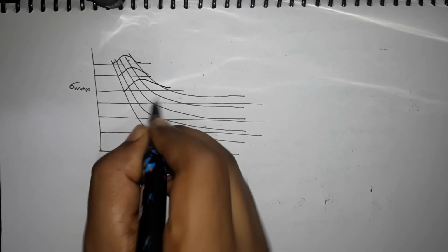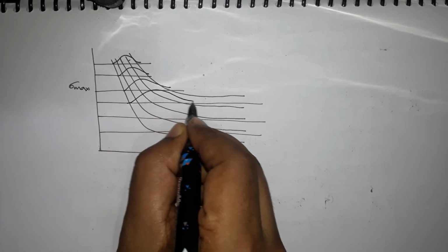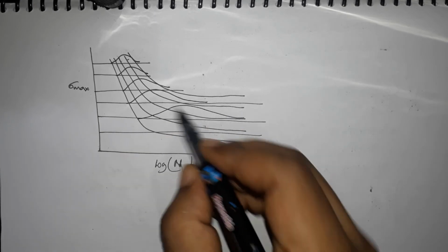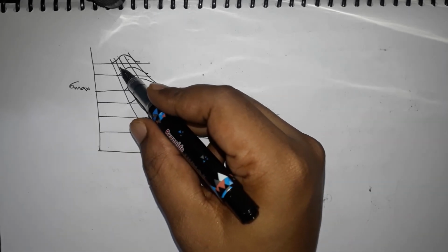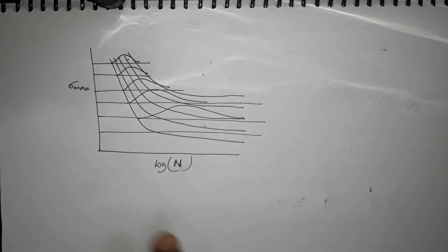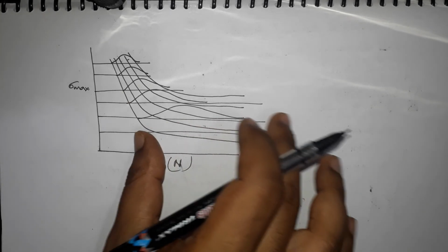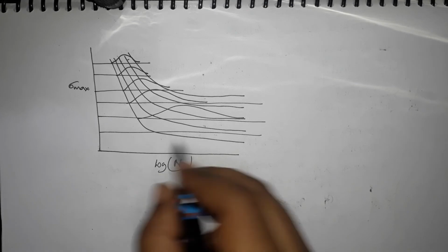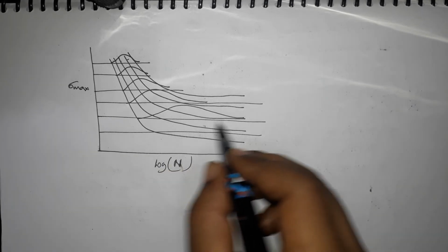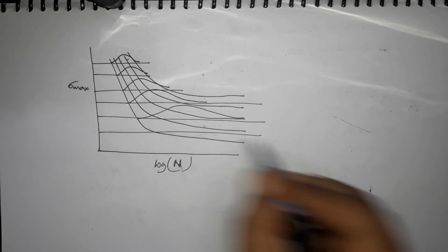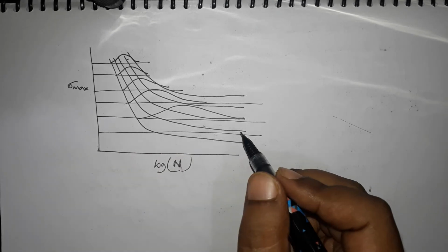Okay, and this has a trend. The trend is that at a higher stress level the number of cycles range is smaller, and as you go lower in the stress, this range increases to a very great amount and you reach a place where you cannot actually capture the whole probability because it hits that endurance limit value.